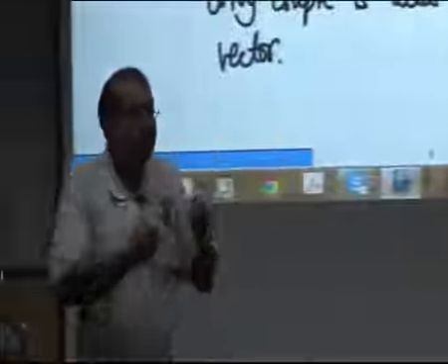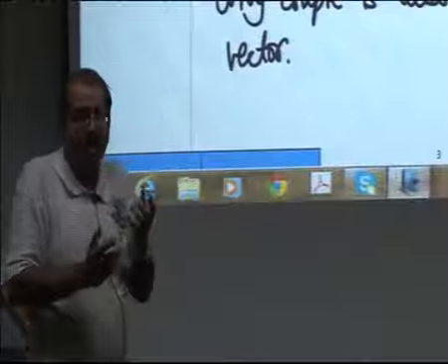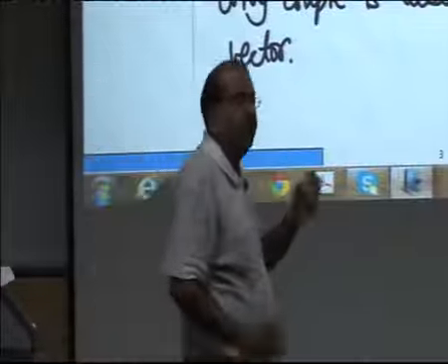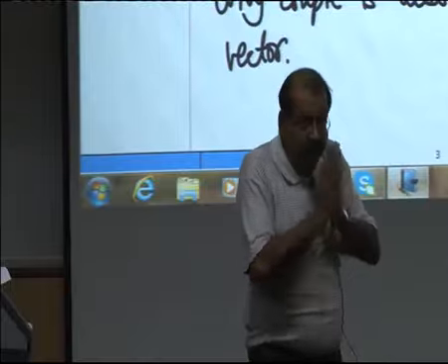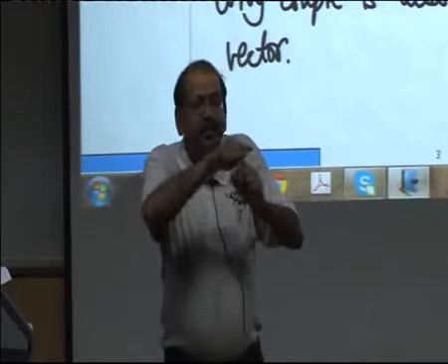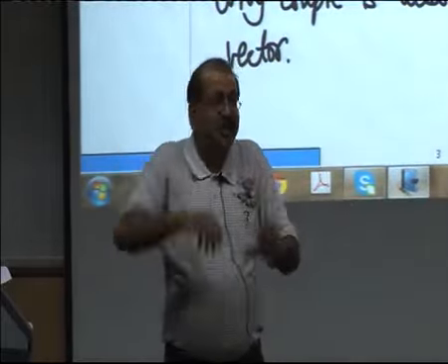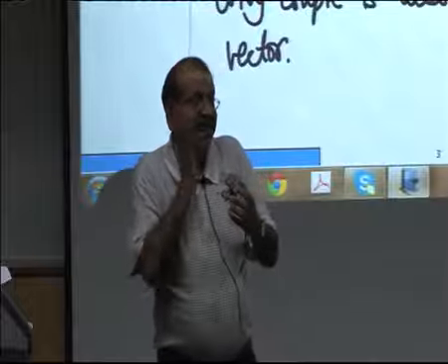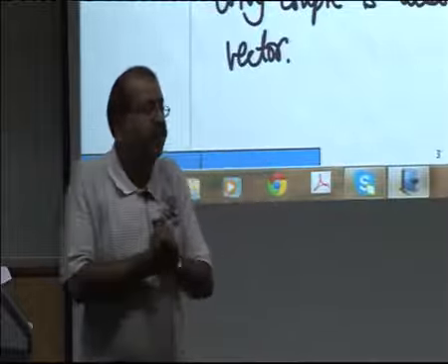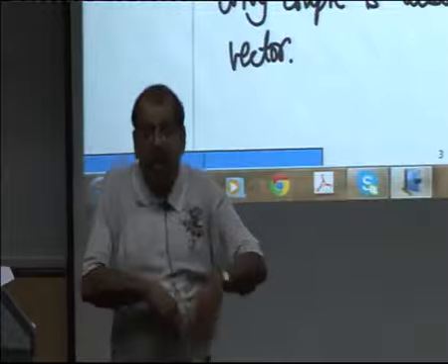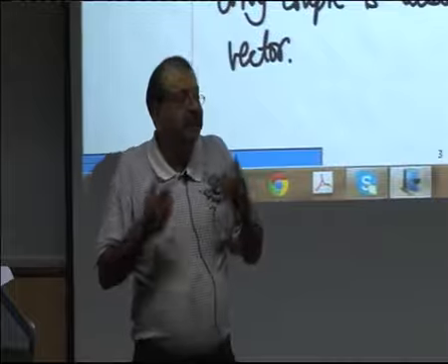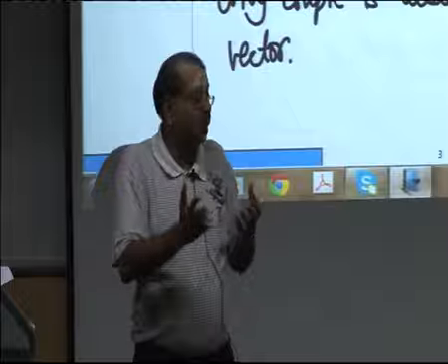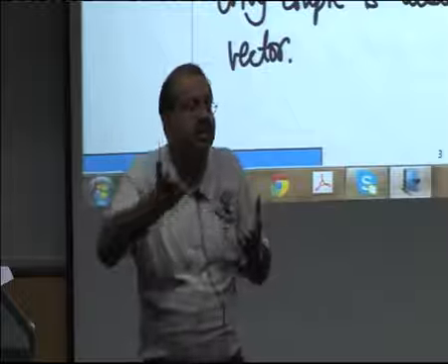I'm not saying you should throw that intuition away. It should stay. But this works well for planar problems. For 3D problems, you will find that the position vectors will have all the three components, and if you try to directly find the moment without using the vector notation, you will end up missing out one or two components, or you may not be able to calculate the distance properly.